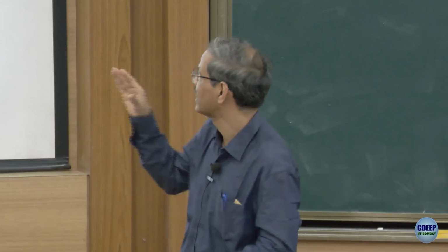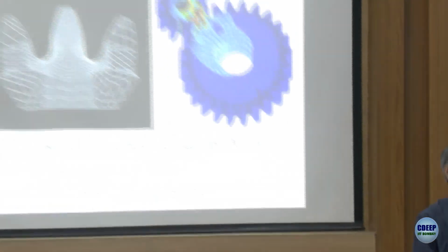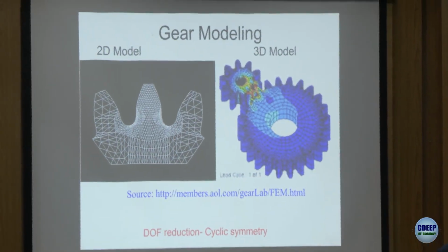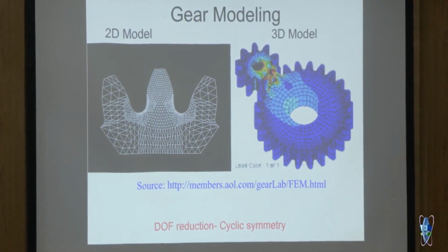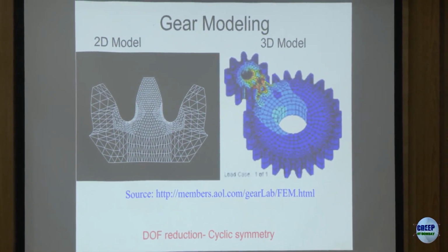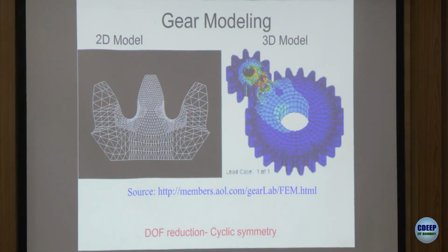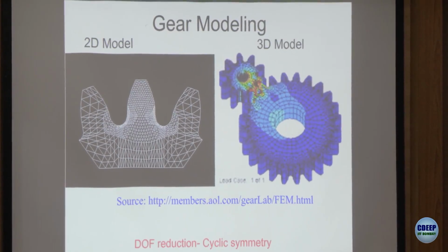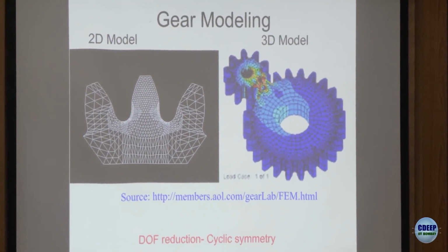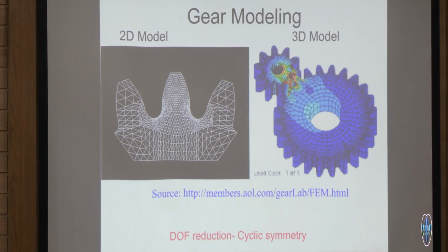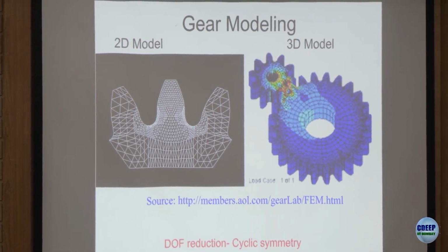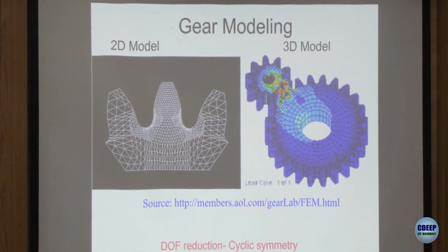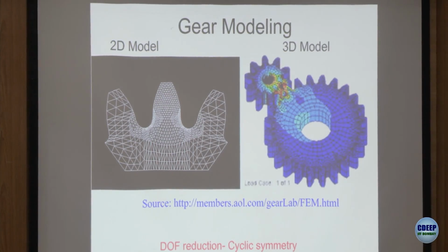So, on the left side I have shown a finite element mesh which has only 2-dimensional elements. When I say 2 dimensions, it is not that they don't have thickness. It is implying that along the thickness direction, the field variable is varying in a known manner, which you can assume, and therefore it is out of finite element computation. Okay, that is the understanding of 1D or 2D or 3D.